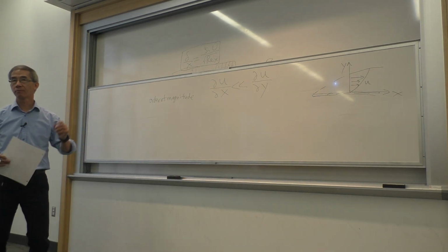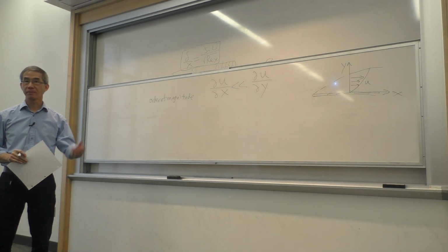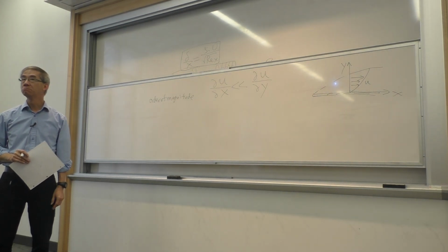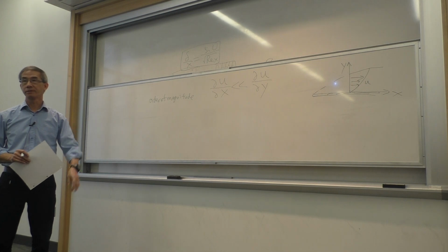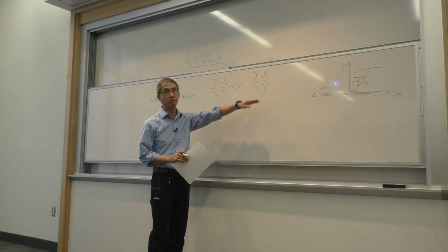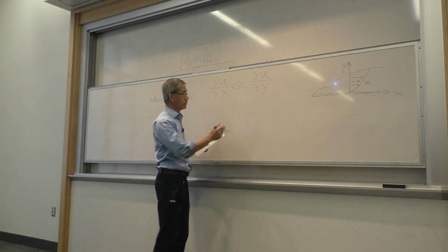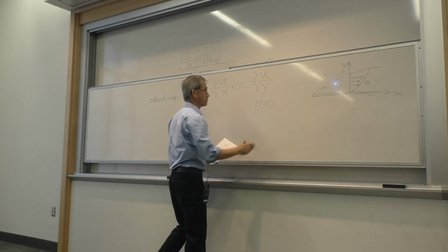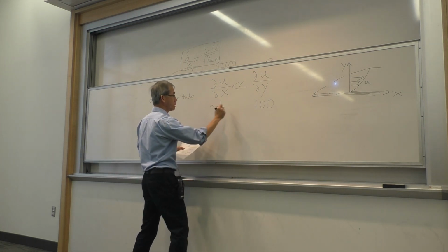Remember the car hood problem? The boundary layer is about 5 feet from the hood. Is how big? Anyone remember? Less than 1/10 of an inch versus 5 foot distance. So the rate of change of the velocity in the vertical direction is much, much greater. If this were, say, just for the sake of argument, about 100, this will be in the order of 1.